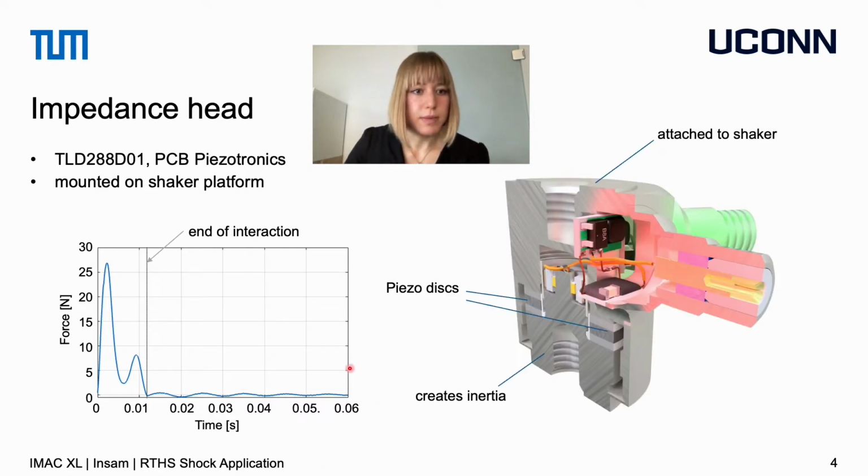Here you can see the piezo discs that measure the acceleration and force data, and this upper end is attached to the shaker, and this side here is the side which is hit by the pendulum. So there is this portion of the sensor that has inertia and creates these forces. And these forces should be compensated in our setup.